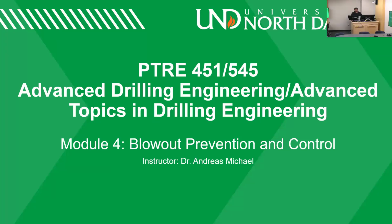So the question is that the SICP is equal to the SIDPP? Yes. Which tells me the kick is completely below the bit, and there's no migration happening. So it's staying the same all the time? Yes. To what value? The 1600.